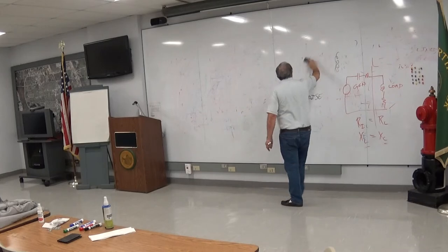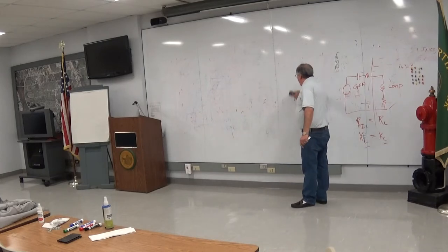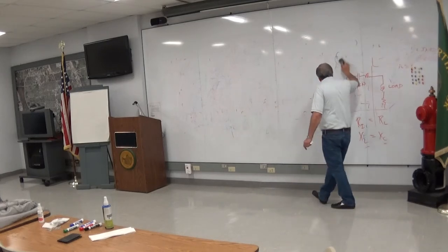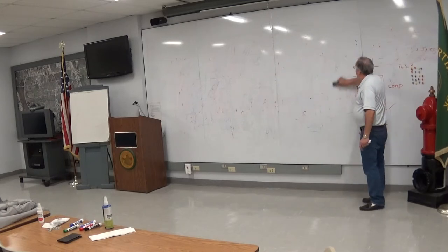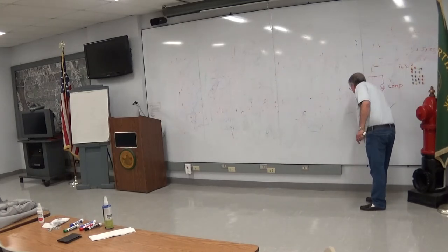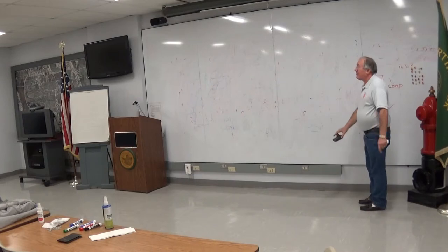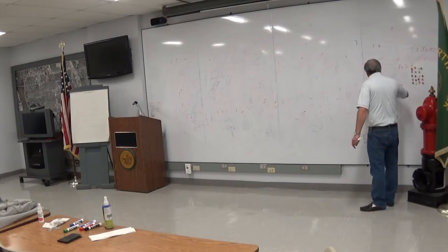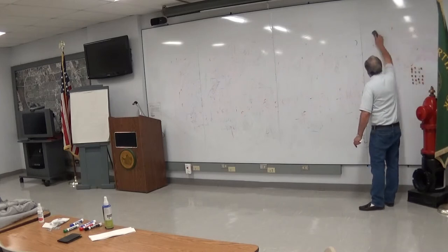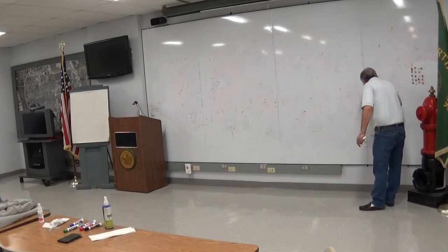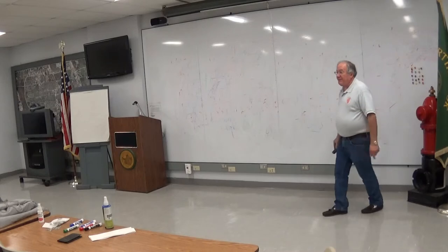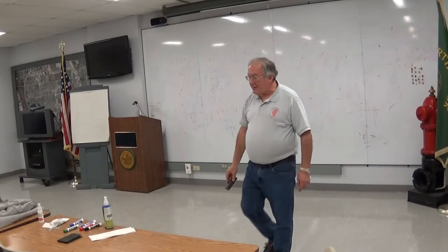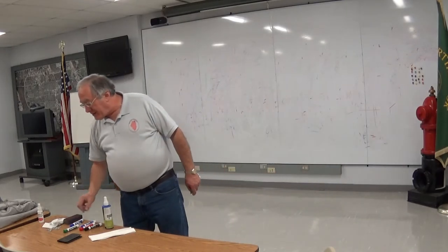So what in the world are they talking about when they talk about 50 ohm coax cable? It has nothing to do with intrinsic resistance. I can guarantee that. What it is, is what's called characteristic impedance. I'll explain that. This stuff isn't just for radio buffs like us, it's for computer guys too. You'll deal with it when you're setting up things like Cat5 cable for Ethernet or whatever.